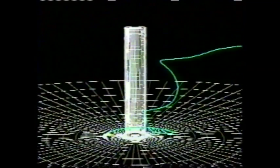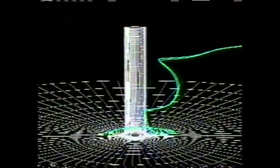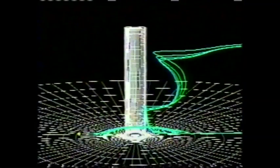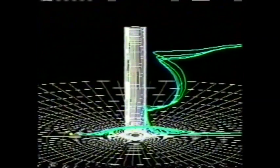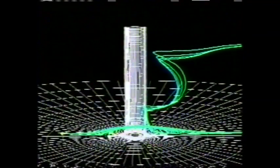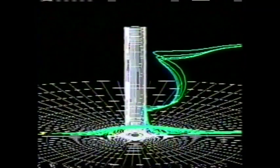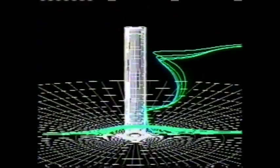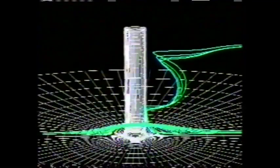I've located my cursor upstream of the post, down near the flat plate, and started to let particle traces go. I'm moving the cursor upstream slowly in the region of the horseshoe vortex and saddle point of separation. As you can see, I'm moving the cursor up and releasing particles at short distances and building up a quick picture of what's happening in this flow field, both upstream and downstream near the plate.